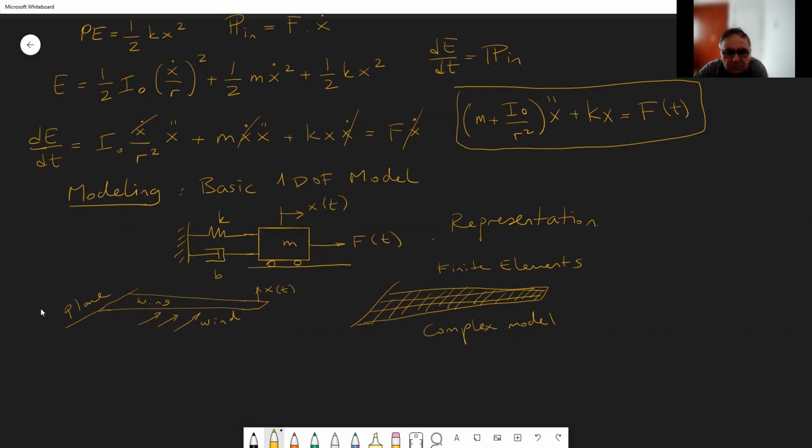Or you can just use the following. Again, you might use a mass, a spring, and a damper. This is the simple one. Obviously, the complex one will be more accurate, and the simple one won't be that accurate, but it's okay for the time being. If you want a very basic result, like the first resonance or something, this might be okay.